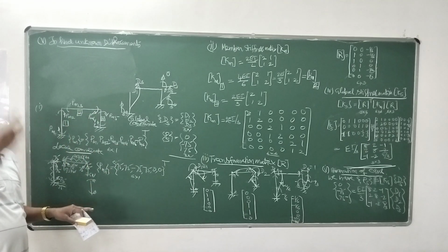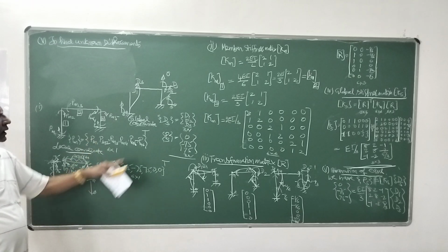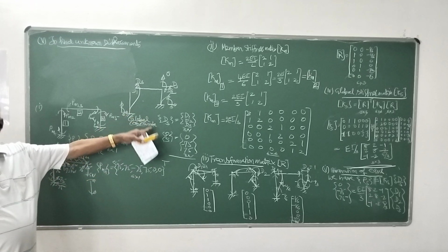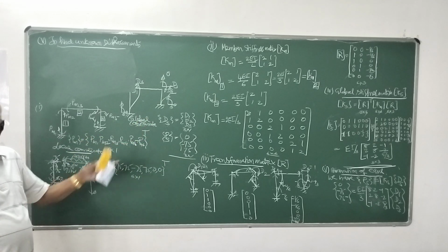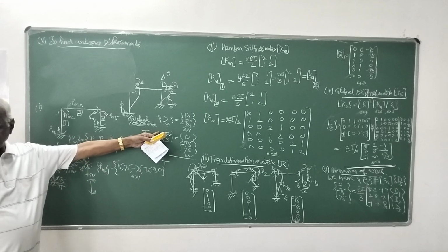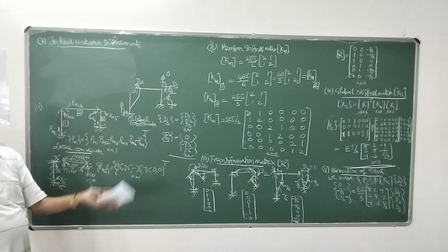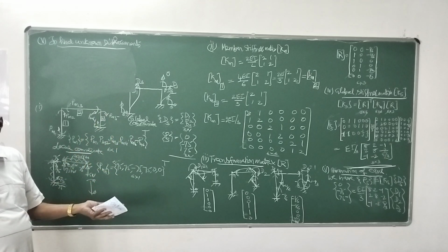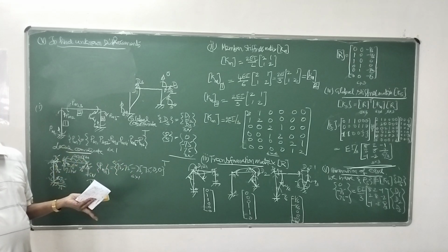You have to resolve all the loads in the global system, and the displacement also should be in the direction of the loads, that is the global direction. Then for the members, you have to determine the internal forces developed within the member corresponding to local coordinates.